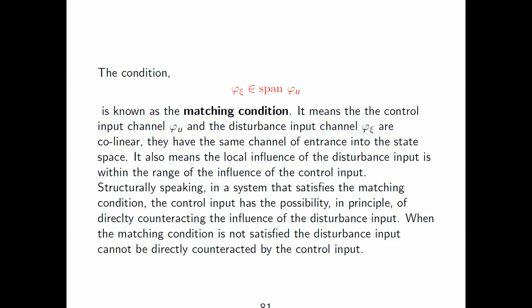And in the worst case, if you go with some motor design called capless, they're trying to use a very, very thin capacitor to reduce the cost and the size. In that case, your bus line voltage is basically a half wave sinusoid, the absolute value of a sine function.